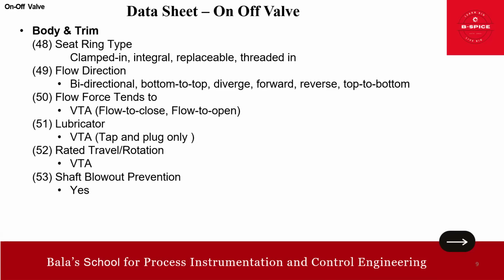During a shaft blowout, the valve internal components separate, allowing high pressure fluid to escape unrestrained. This can result in fires, vapor cloud expansion, or a hazardous situation. That is why we are going for it.